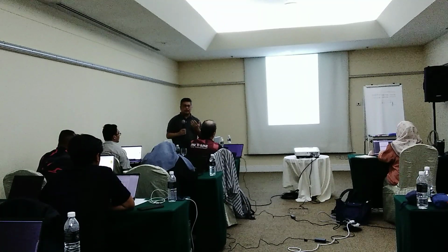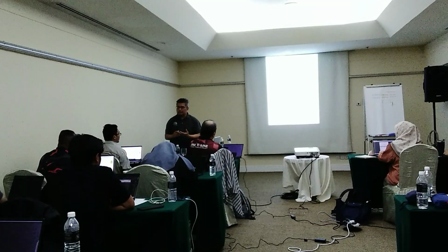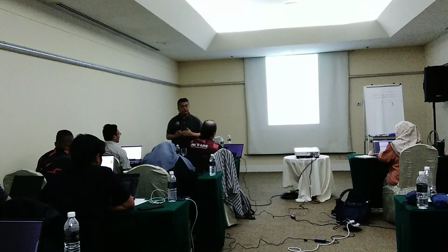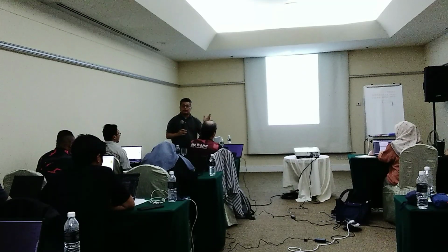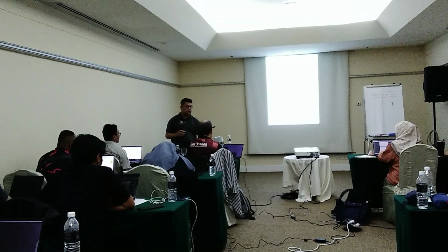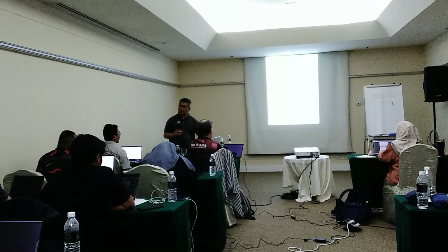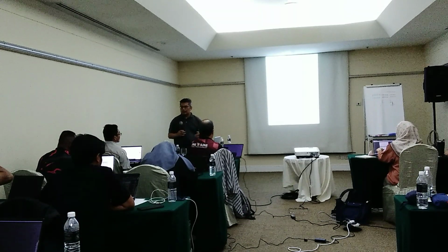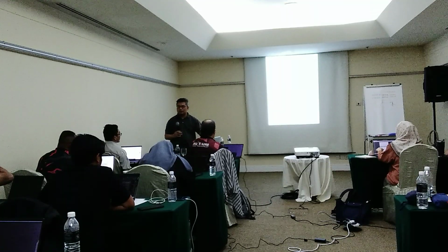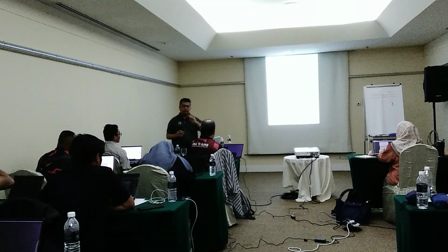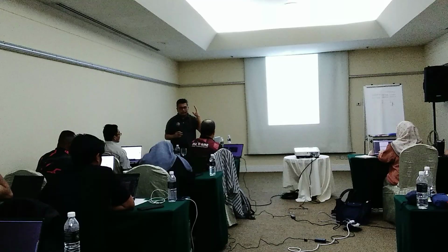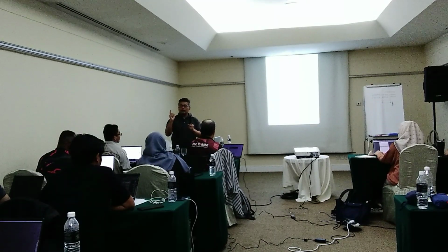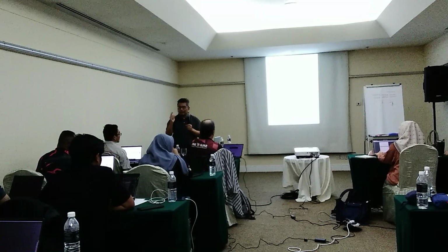Once the process creates a huge amount of defects, you cannot totally stop the process, but you need to put the process under review, under supervision, or under special attention. So when you put your process under special attention, definitely one of the things you need to do is your control plan and your control charts. Why? Because once you put the process under control, all inputs need to have control charts.